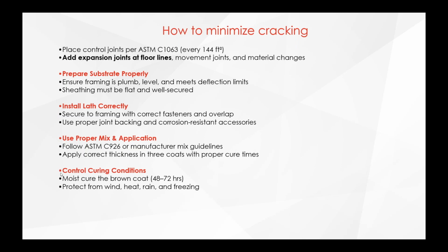Control that moist cure. I've seen this a lot, okay? I always recommend to contractors to take photo documentation of your moist cure. If a building does crack, that consultant is just going to assume that you did not do any moist cure, and it's going to be up to you to prove it. So take photo documentation. You can prove that. Plan for weather. Don't ever let a GC say, oh, it's got to be done by this date. You go and do it, and maybe it's too hot, too windy, something happens, and at the end, if you try to go back and say, well, they made me do it because of X, Y, and Z, you're always going to take responsibility as the builder because they'll always say the builder should know better.